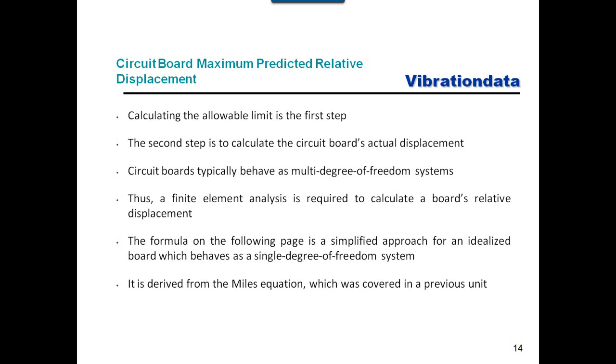And we're also going to talk about a reintroduced Miles equation, which is just a quick hand calculation method for determining the response of a single degree of freedom system to a PSD base input. Now, some of you that are particularly astute are saying, hey, wait a minute, didn't you teach us a number of webinars ago a better method than Miles that you sometimes refer to as the general method? And the answer is yes, and I think as a bonus I'll include that method here at the end of this presentation. But just to be consistent with Steinberg, we're going to use Miles' equation.